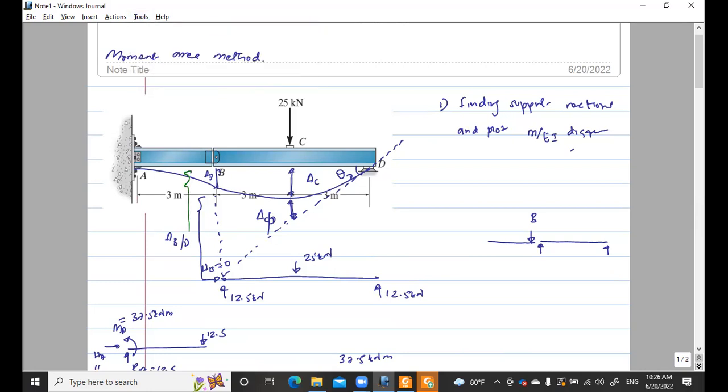When we look at whether we can find this value, yes, we can find the deflection here using this component, and tangential deviation here using this component. So we can find this, and half of that is this value. So with the available calculations and derivations, we were able to find delta C.